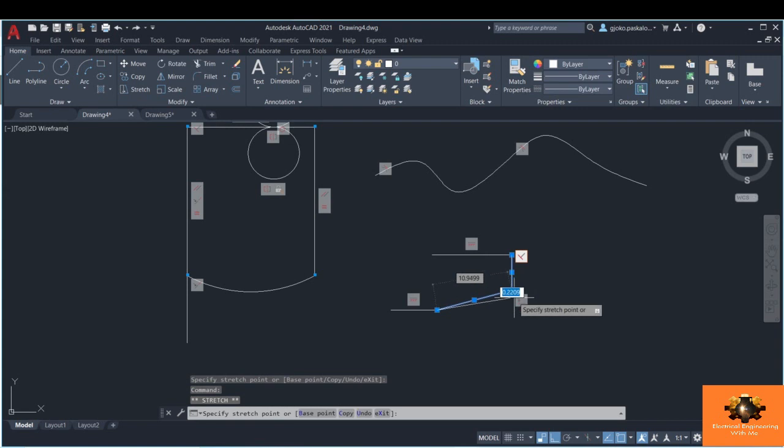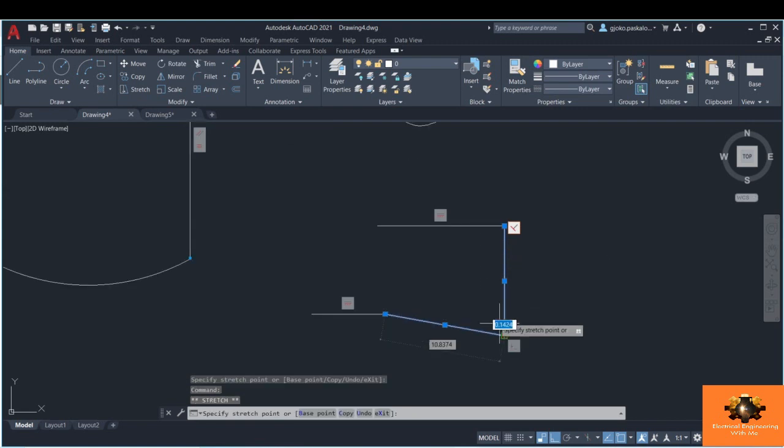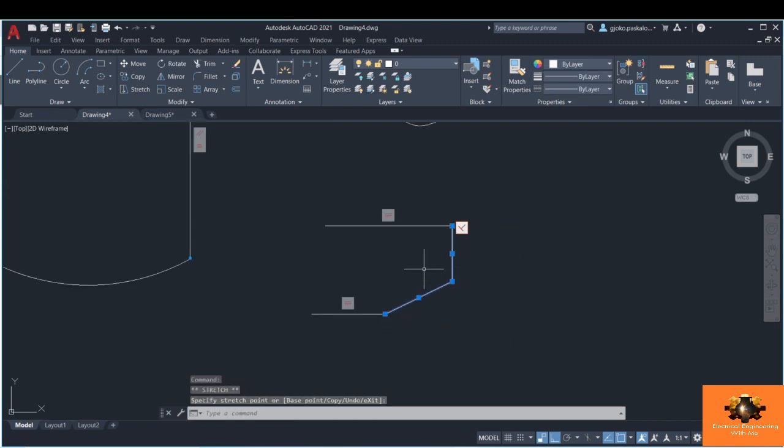So I use the ortho mode, and you can see that horizontal constraints were made on some of the lines, and actually with this option the constraints will be assigned quite strictly. You can see I have constraints on all the lines, even on the dots between the lines, so the moving capability of the drawing is limited.